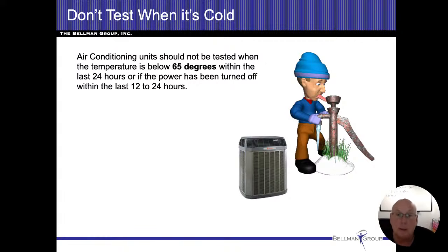Now, the reasoning why we don't want to test air conditioners at a lower temperature, I need you to go back to your memories a little bit when I showed that compressor out there earlier. An air compressor can only compress air. All right. If I try to push liquid through that air compressor, then I'm going to damage that air compressor, plain and simple.